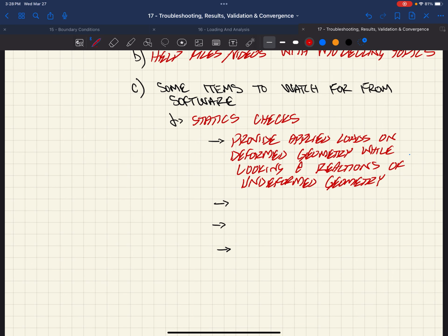It's essentially quantifying, is your load path sufficient? Does equilibrium make sense? Do we have large displacements or relatively small displacements? When we derived all of our elements, we made this assumption that our displacements were small enough that we could conduct equilibrium on the undeformed geometry.